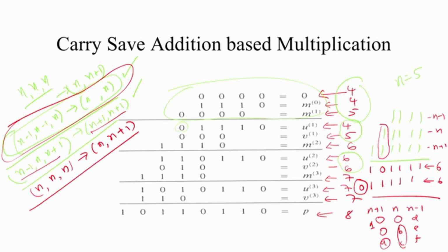So whatever this creates will be some bit here, and whatever this creates as a carry is going to be 1. Since these two are zeros, this particular stage will never generate a carry, because 2 of the 3 bits are zeros, so I cannot generate a carry. So this carry will always be 0.